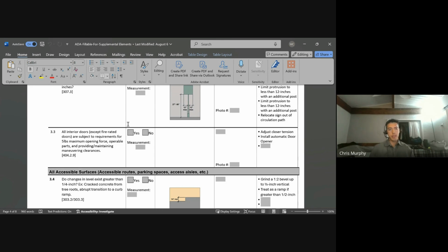The other aspect behind measuring door opening force is that it's measured once the door seal has been broken, so that the air pressure on both sides of the door has had an opportunity to equalize. Then you start measuring until you get to a full 90-degree opening.